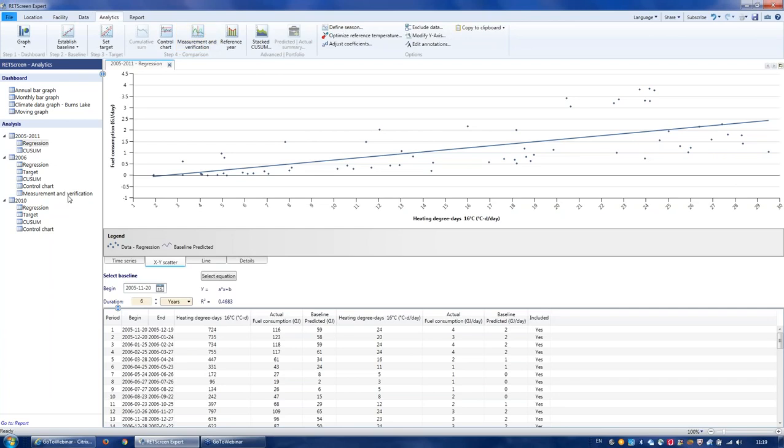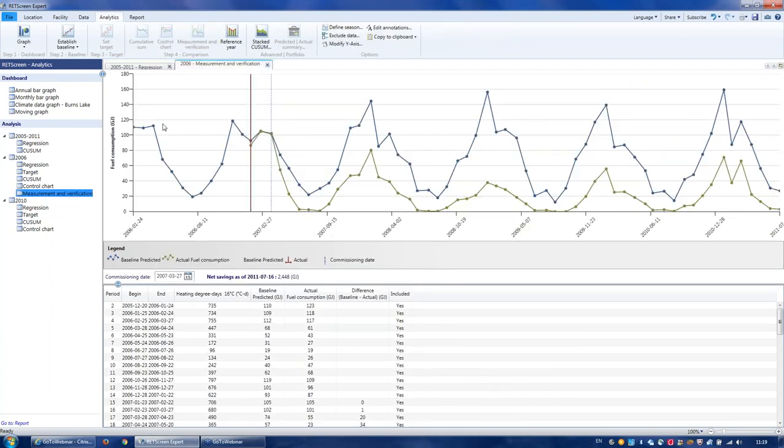a standardized graph. So just quickly to show you, this is given the historical and baseline information. This is the baseline year consumption of the building for natural gas. And if you did nothing to that building, in this case there was a high efficiency gas boiler put in. So if they'd done nothing, the blue line, given the heating degree days, the outdoor temperature, this is what you would have expected the consumption to be, the blue line.